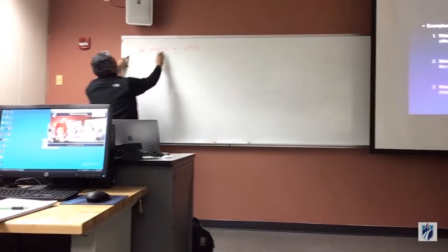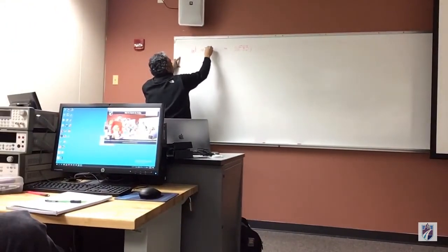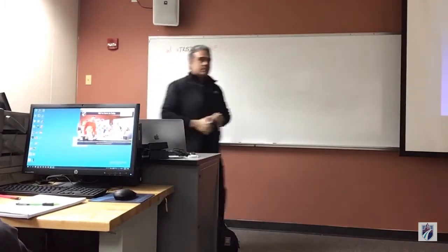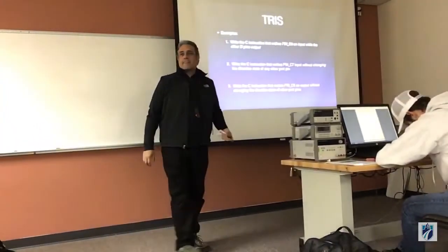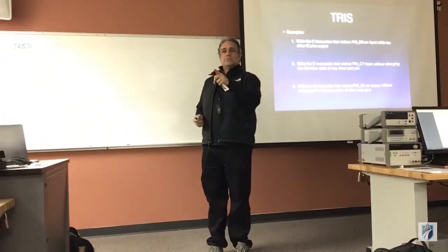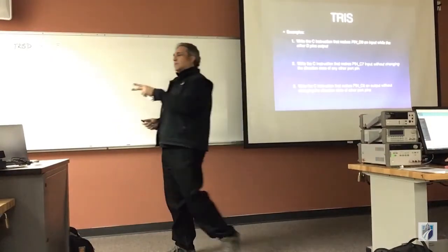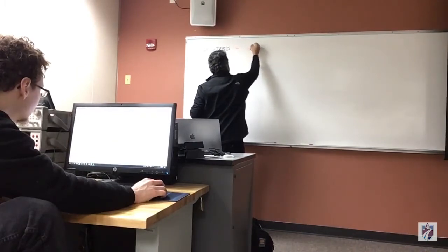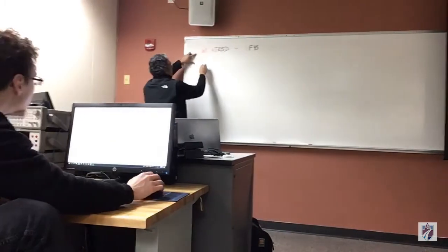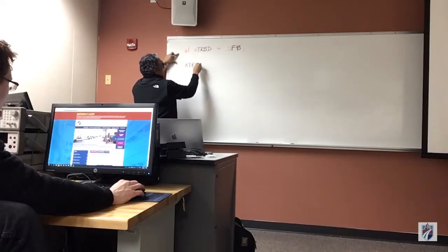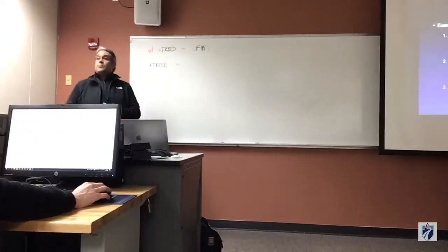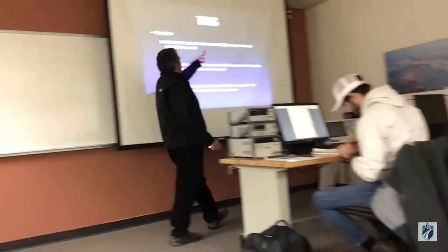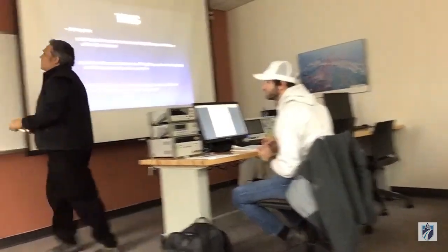So this should be Tris D, and then somebody give me the number of Tris D. Tris A was 92. So B will be 93, 94, 95. So Tris D, and then you get the content of Tris D is going to be equal to, port D has 8 elements, and I want D0 as an input, while the other pins are an output.